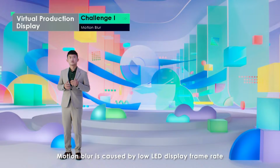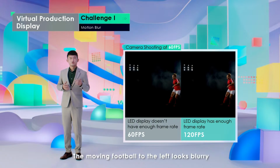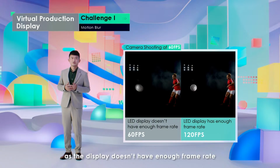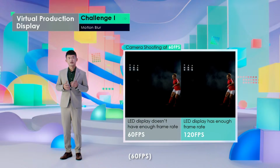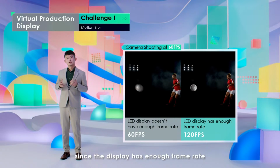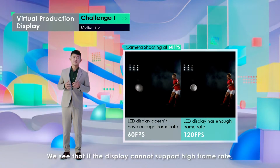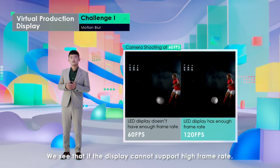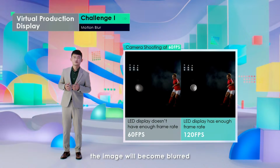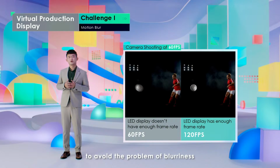Motion blur is caused by low LED display frame rate. These are taken in 60 FPS. The moving football to the left looks blurry as the display doesn't have enough frame rate, 60 FPS. We can see the football clearly to the left since the display has enough frame rate, 120 FPS. We see that if the display cannot support high frame rate, the image will become blurred. We need to increase the display frame rate to avoid the problem of blurriness.